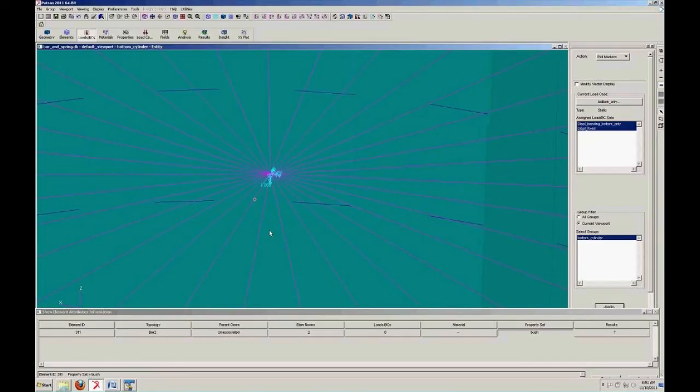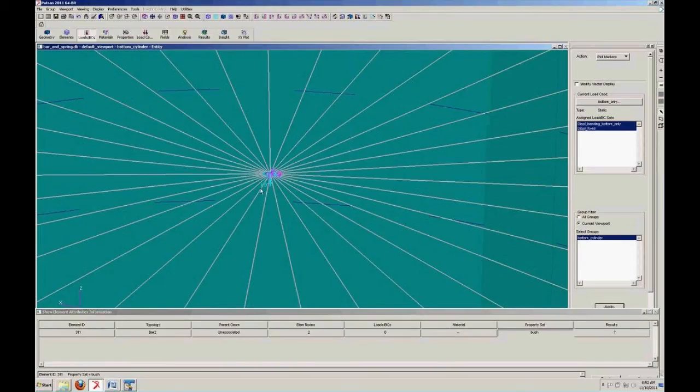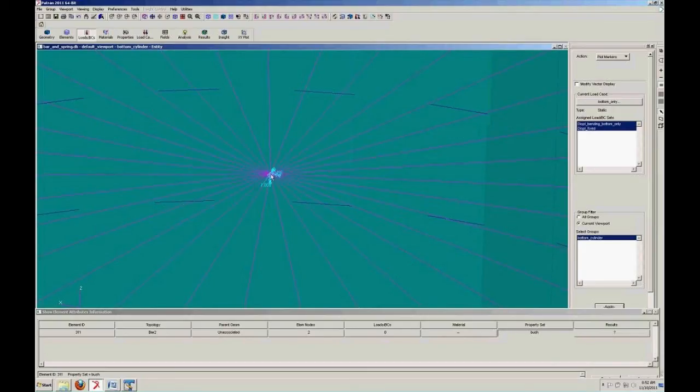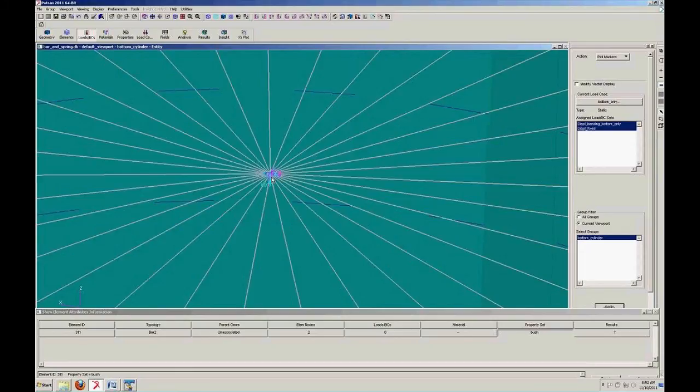So, long story short, if you want to see what the stiffness of your model is, put a load on it. You put a load on it, and then you look at the displacements. And F equals Kx, so the stiffness is going to be the force you applied divided by the displacement that you get. And that gives you a rough ballpark for the stiffness of this area. In my case, I try to be a little clever about it. I apply a unit displacement because, again, F equals Kx. So if x is 1.0, then basically the constraint force of this applied displacement is going to be the stiffness of this area.